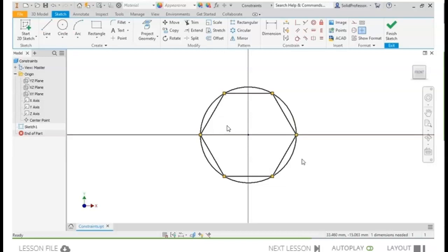Be sure to pay close attention to these small icons that pop up next to your pointer. If you don't, you may be creating constraints without knowing it, which can be frustrating when the sketch doesn't behave as you're expecting. The automatic constraint here with the current sketch was very simple, but as your sketches get more complex, so do the potential constraints.